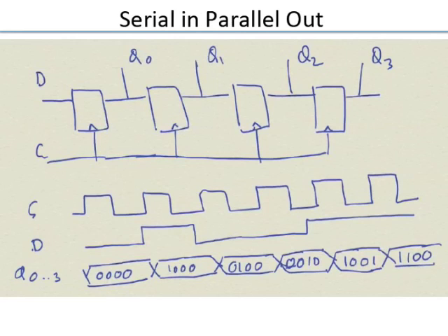Now one of the problems with this is that, as you are shifting in, what is happening is this Q0, Q1, Q2, Q3, they are changing. Now sometimes it's kind of not nice. You have a certain pattern which you are happy with, now you want to change to another pattern. But to change it, you need to keep shifting things. And for those clock cycles, these patterns are all changing, Q1, Q2, everything is toggling. And that can be a problem.